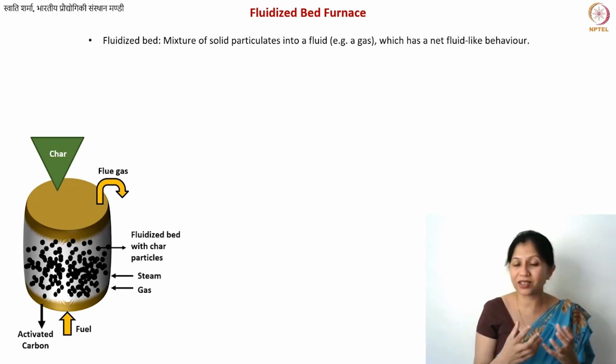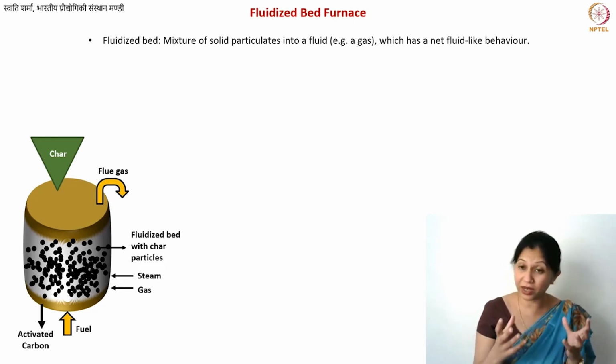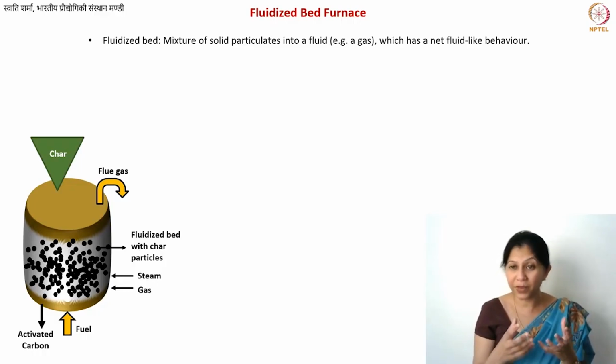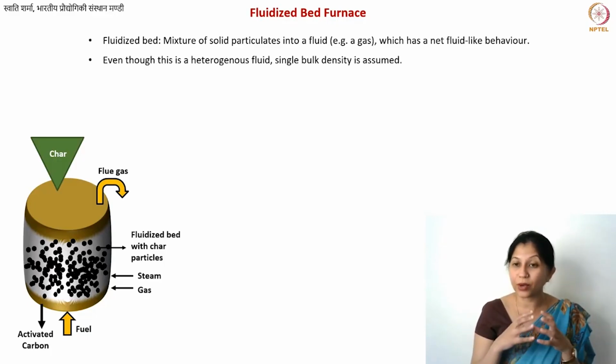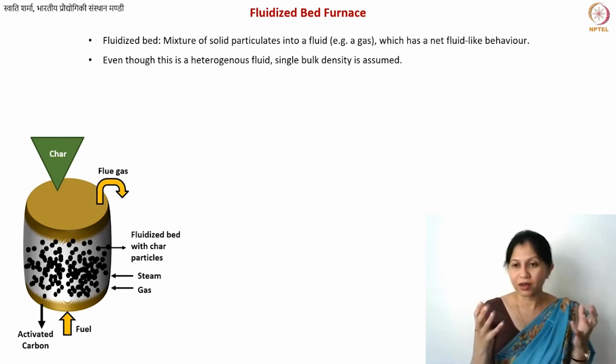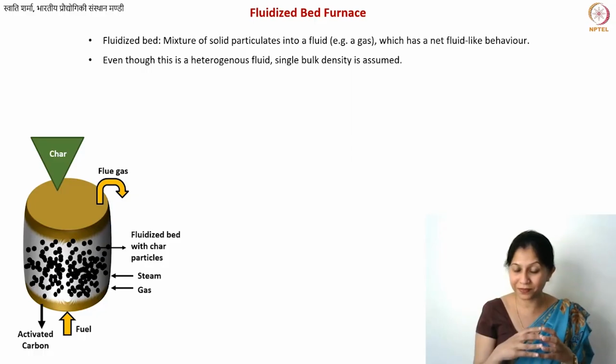So they are like suspended solid particles in a fluid, and the fluid can, by the way, also be a gas. So what will happen is you make this mixture in such a way, and also you create so much turbulence in that fluid, that your entire mixture of solid particles in the fluid behaves like one single fluid. So that is the idea of any fluidized bed reactor.